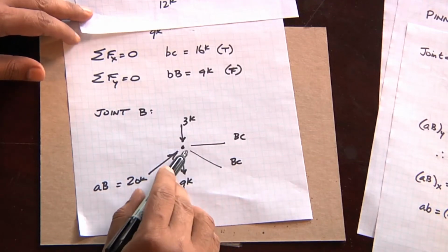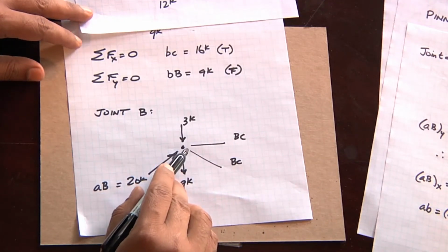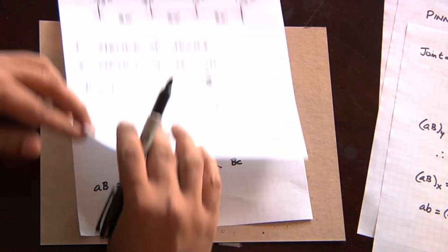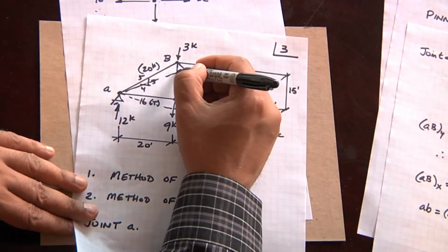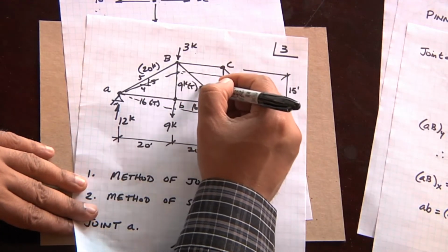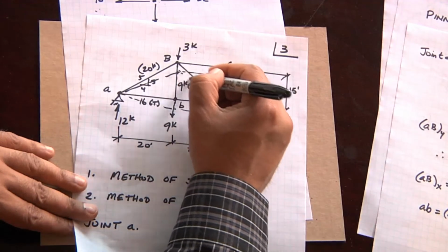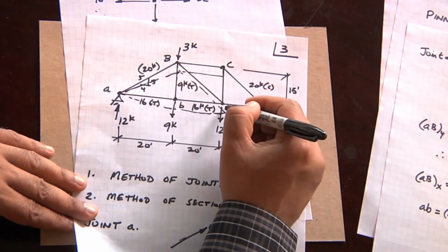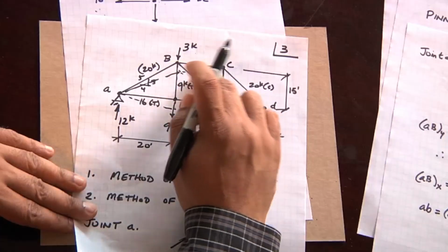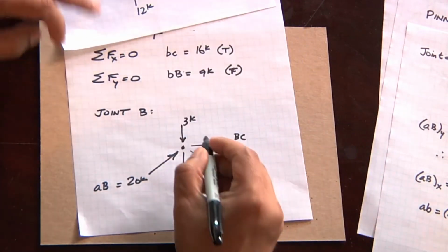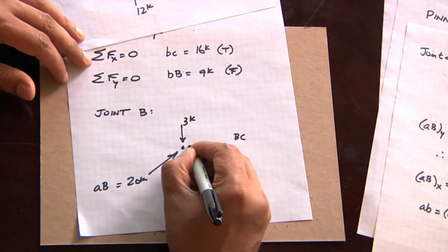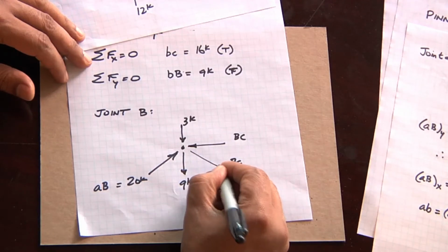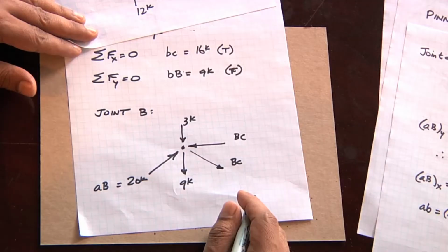In this case, from looking at the deflected shape, the diagonal chord will be extending, so it is going to be in tension. The top chord is going to be in compression, and I'll prove that to you in a moment. If we draw it in there for now, that's going to be the final load diagram.